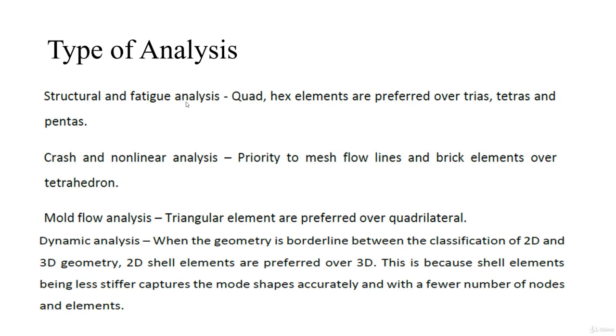Likewise, depending on the type of analysis, for example, if you are performing mold flow analysis, then instead of all other elements, triangular elements are more preferred over quadrilateral elements. So coming to the dynamic analysis, and depending on the type of geometry also, we have lots of types of elements that can be selected.